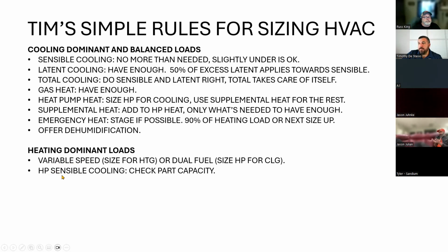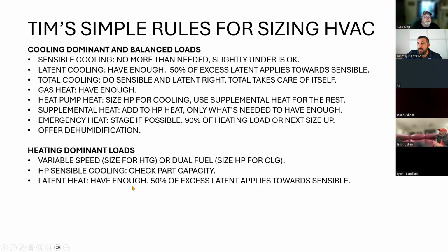Sensible cooling for a heat pump. Obviously, you're sizing this heat pump for heating, so you're going to have to check your part load capacity on cooling and make sure that it can turn down enough. Latent heat, again, have enough. That is always going to be the case with latent heat. You've got to meet your latent heat load. And again, you can apply 50% of your excess latent towards sensible.